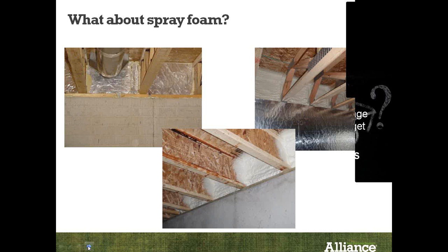And then, what about spray foam or other rigid board products? These are the best practices that we see. When we have impermeable installations, we can address a lot of these surface temperature areas, and we can increase these surface temperature points by installing vapor impermeable insulation in these areas. Now, these are all installed inside the home. They can be installed outside the home also.